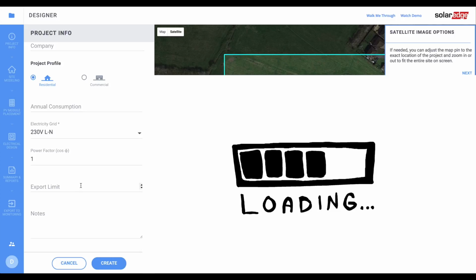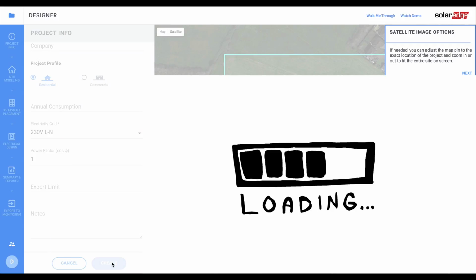And we won't bother with the export limits, but in the videos you've seen before, you'll know by basic approvals you can have like 3.68 kilowatt export. If you're going to have more than that, then you need to get your DNO approval, and obviously I've gone through that process to have 6 kilowatts. But this gives you some insight.